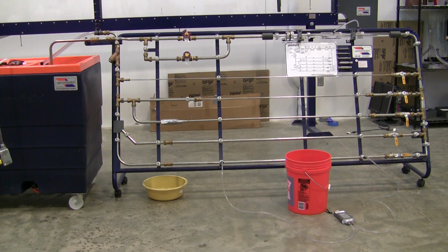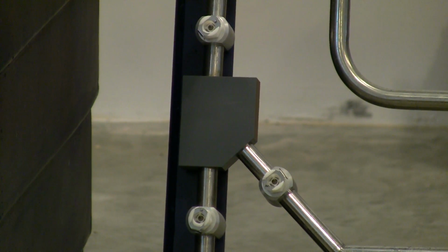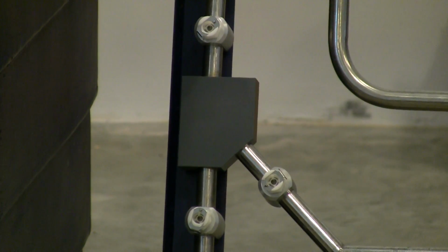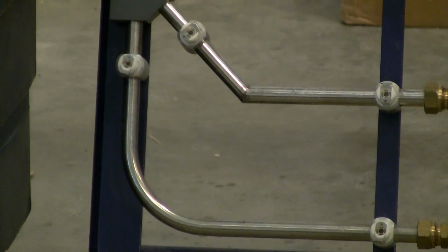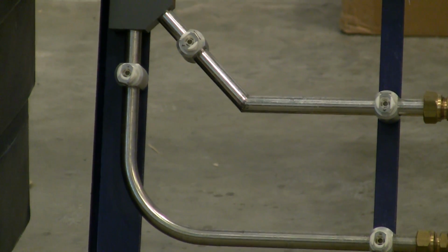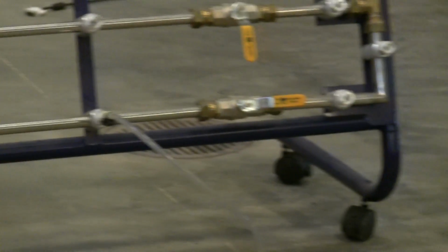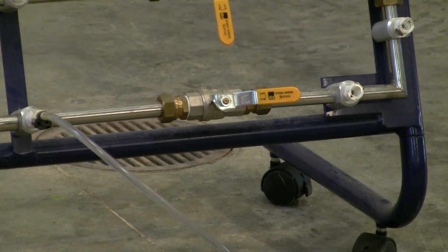First of all, we're going to go through the 45-degree Y. And let me bring that up on screen here, the 45-degree Y. And you can see the tap upstream and the tap downstream. We're going to be going in a straight line. We haven't yet directed flow sideways out of that, so that is the 45-degree Y. Item 6 on your figure, included with the lab handout, is the long radius 90-degree bend. Next, we'll move on to the ball valve. The ball valve is here. The ball valve is currently open. Next will be the 90-degree T.